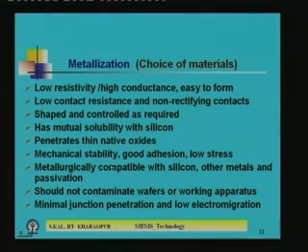So, that means low stress is desirable, and mechanical stability should be high, because when you are patterning say 100 or 1000 microns or millimeter length, and the width is of the order of say 5 micrometer to 10 micrometer, then these narrow lines in subsequent processes must be mechanically stable.